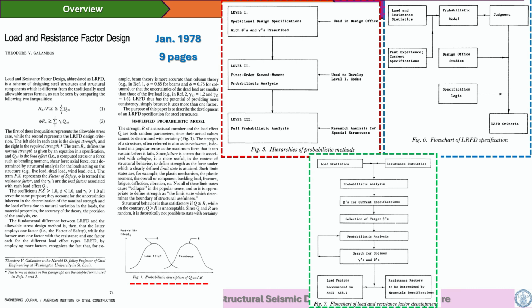So really, we want to know the inherent safety of the structure based on probabilistic analysis. And more importantly, if we expand this to include both the demand side and the capacity side, weighting also the safety factor through the confidence value, we will get the full probabilistic methods. Of course, this level seems too advanced, but it is nowadays widely used by insurance, for example, because it's the way that we can even combine different hazards.